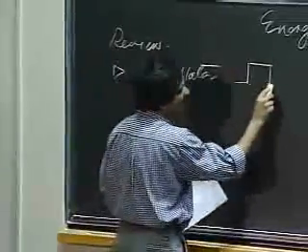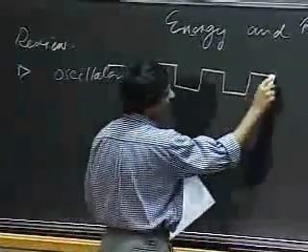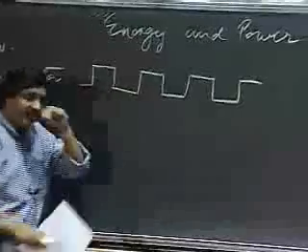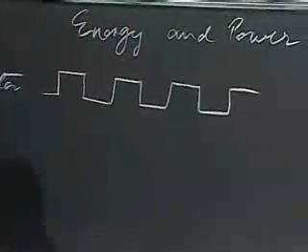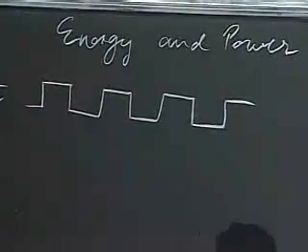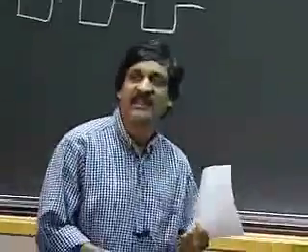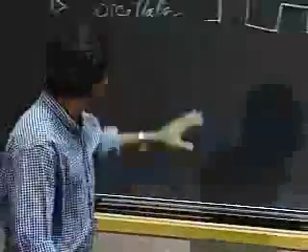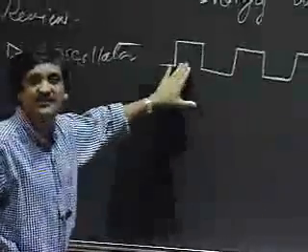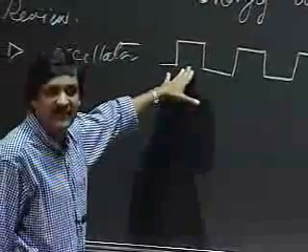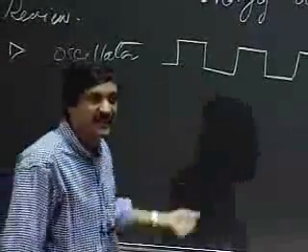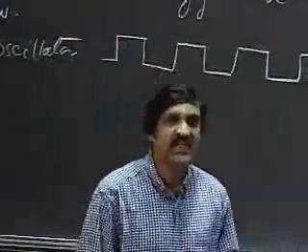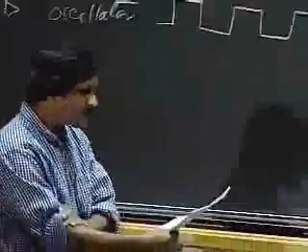At the output, you would get a square wave. Throughout the course, we've talked about getting square wave inputs, and this is one example of how you can actually produce a square wave, pretty much from first principles using a capacitor, resistors, and an op-amp.